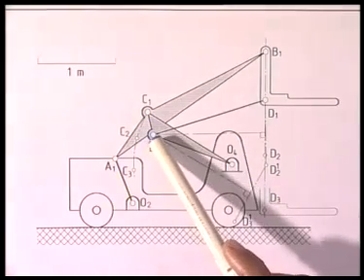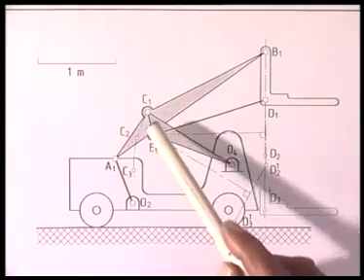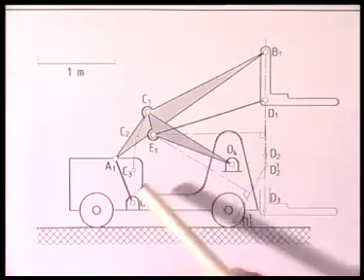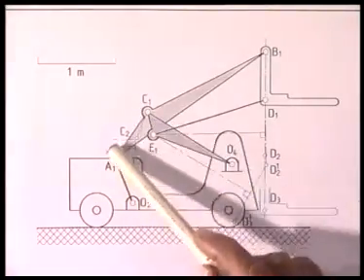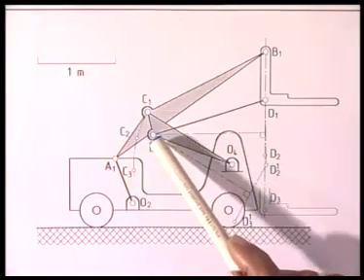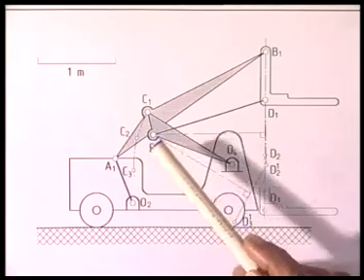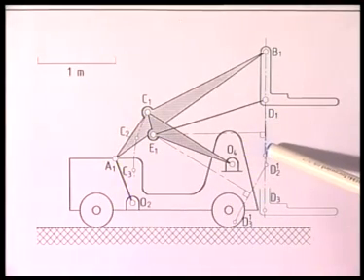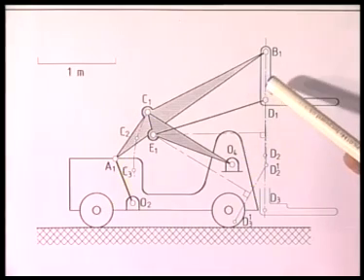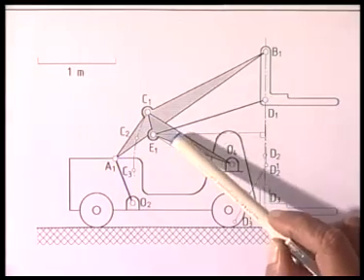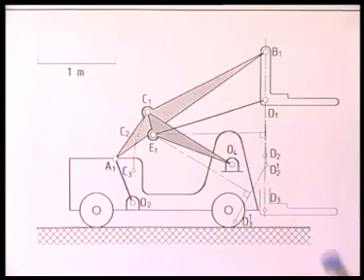To determine this E1, I make again a kinematic inversion keeping this link fixed, that is the follower link of this O2AC04, this 4-bar linkage, the follower link I hold fixed at its first position and determine the inverted positions of D1, generating the same relative movement but holding this link 4 fixed.